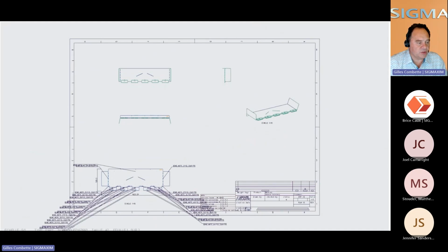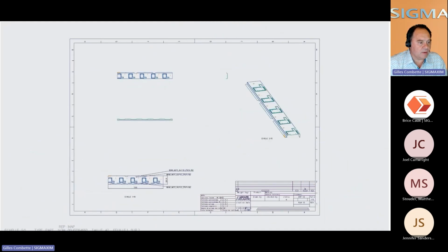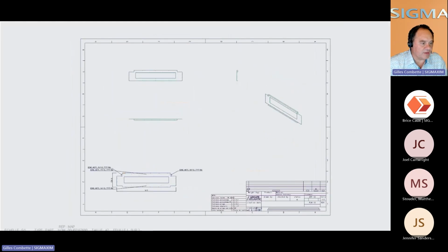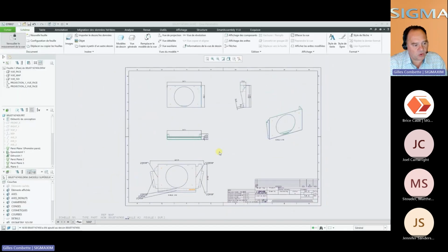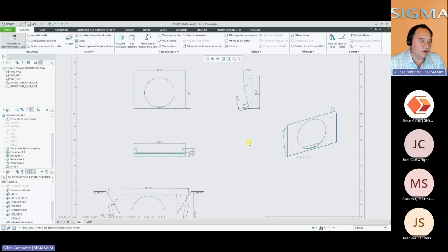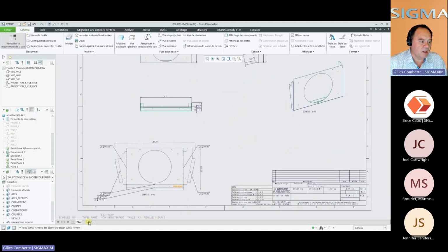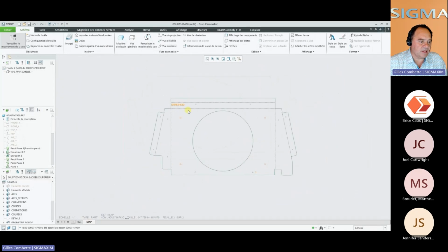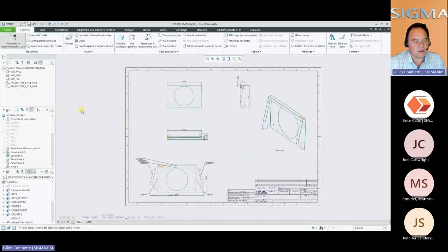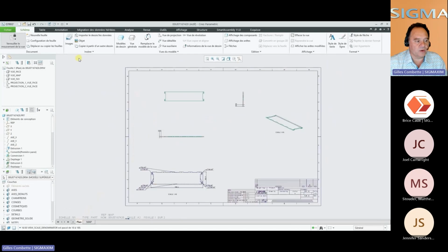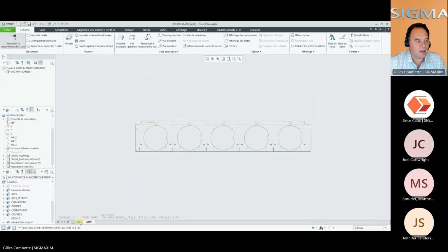2 pages 2D drawing. Page 1, a detailed drawing with 3D views and a small flat view. And page 2, a scale 1, no border 3D view. So this is page 1. Dimensions are added automatically, and page 2, the 2D flat pattern with no border for the DXF output.